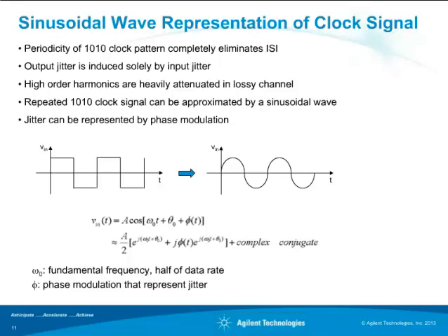In principle, the synchronous clock can be simulated. Actually, in the IBIS-AMI approach, this effect can be taken into account because the Rx AMI model could return its clock times, and that is used by ADS to center the eye in the data signal.